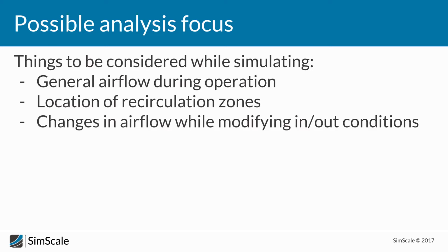Very often we will be facing situations when a single room will be operating under different conditions. We can have a laminar chamber. This is exactly what we'll be talking about today. We can have a reaction chamber that will have a blower or a suction, or a laminar chamber that is providing access to different tools. Changing the flow and airflow conditions might be significant, especially for taking a look at possible hazardous conditions, when one of the fans is malfunctioning and we would like to see whether this poses some kind of threat for people who are operating within the room itself.